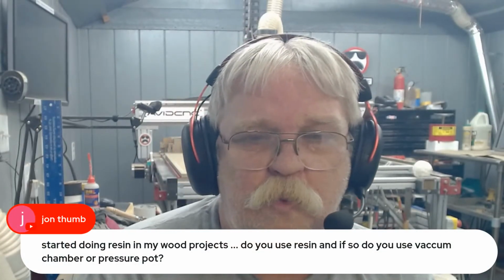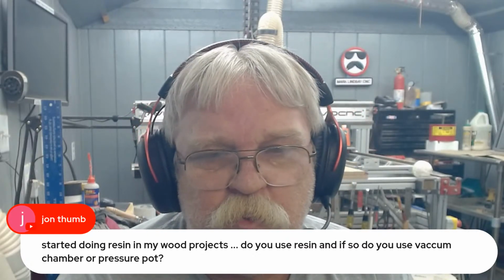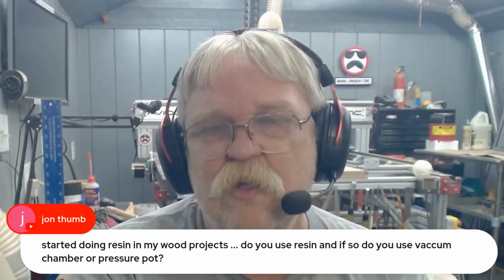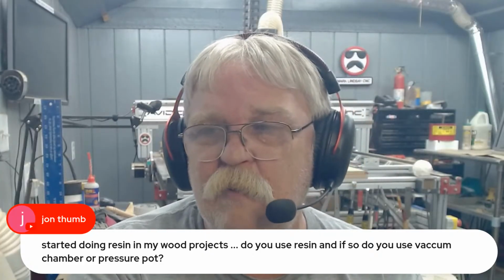Okay, John Thumb wants to know. Started doing resin in my wood projects. Do you use resin? At times, yes. And if so, do you use a vacuum chamber or pressure pot? For resin, you want to use a pressure pot. You don't want to use a vacuum chamber. Vacuum chambers are more for making latex molds, to degas the latex when you mix it. It'll pull all the air out and what have you.